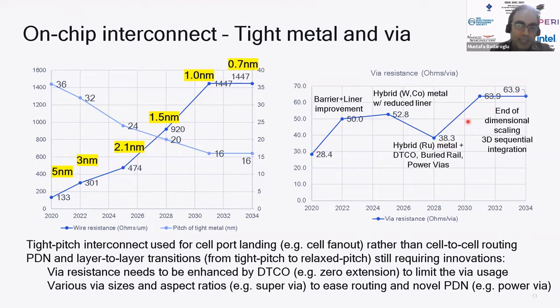So that's why the technology has invested a lot in via resistance improvement by alignment control, by material change, barrier liner technology, and has kept the vertical via resistance relatively stable and projected to remain the same across multi-node generations. Actually, this needs to be enabled because even if you have a 3D power delivery solution, you need to go through that kind of via layer to be able to deliver the current to the cell, or distribute to the other layers, other tiers.